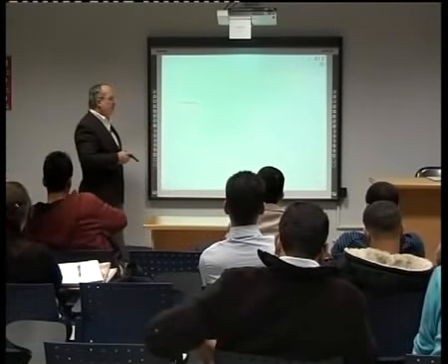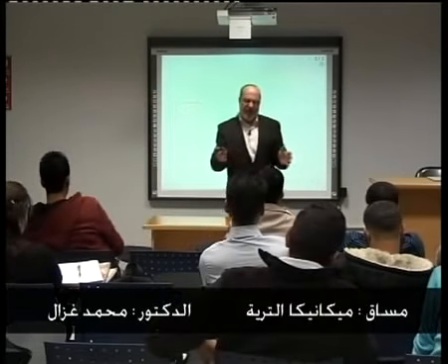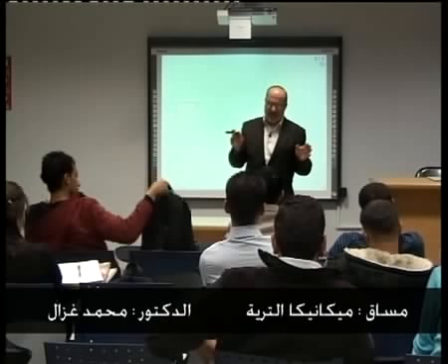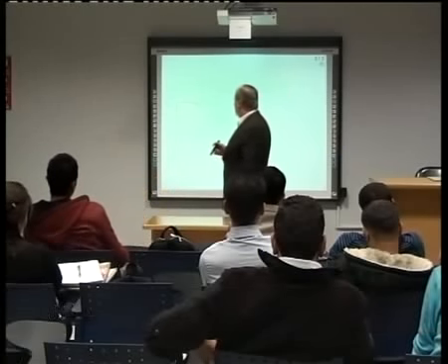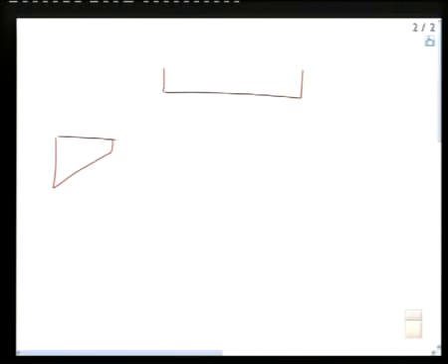Now, I have a question for you. Did you take anything on the design of foundations? You didn't study this. But you may know that, for example, this is the dam, and this is the pressure under the dam. Usually we use the maximum value when we make reinforcement.